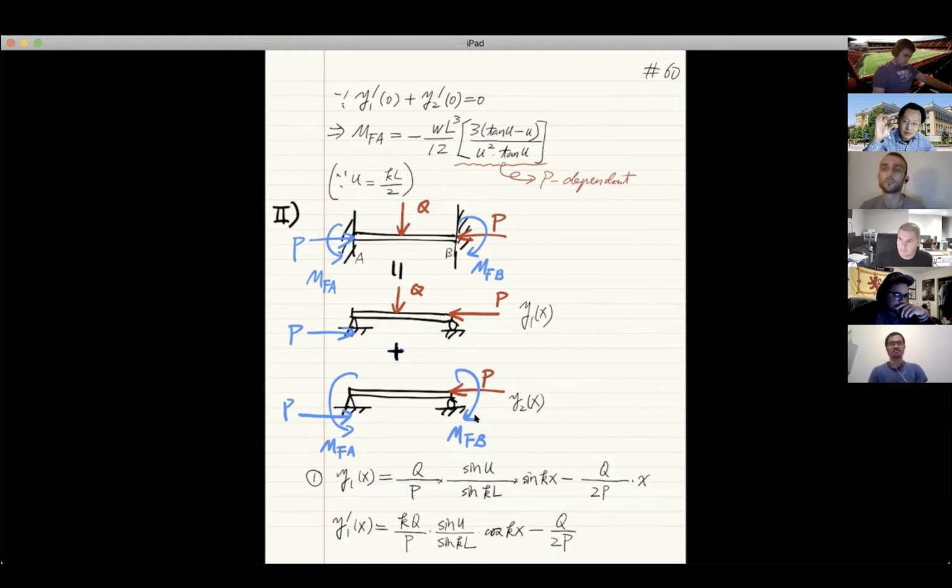If you have these initial deflections, and the P will be applied to this initial deflection, which means that the amount of the amplification that will be distributed to Q and distributed to MFA and MFB is all from P, not half P. So you cannot divide it by half. You cannot divide it by half to say that this half of it goes to it, because the implication from the loading axial force on Q in this case is the whole P, not half the P.